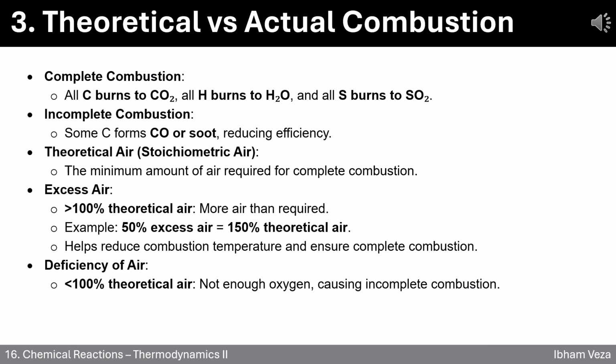On the other hand, when there's a deficiency of air, below 100%, we risk incomplete combustion, which leads to lower efficiency and more pollutants. Balancing this air-fuel mixture is crucial for optimizing performance in any combustion system.